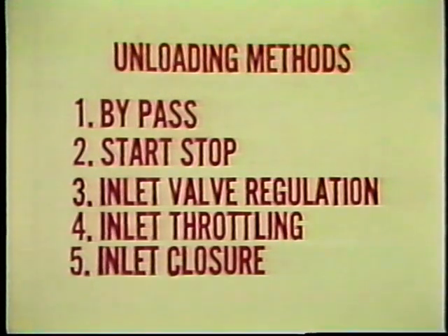There are several methods for unloading a compressor in use today. Here are some we'll examine: bypass, start-stop, inlet valve regulation, inlet throttling, and inlet closure. The first method is called bypass. With this technique, we bleed the compressed air to the atmosphere at high pressure. Unfortunately, this type of control causes the compressor to run under full load at all times, which is hard on the compressor and wastes energy.